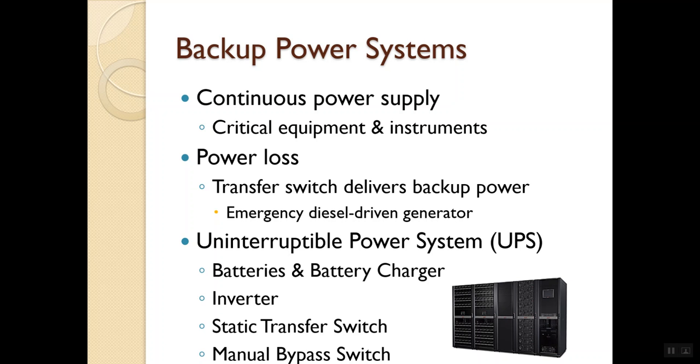And so what we do in industry is all the operator stations, all the control stations, run on a battery all the time. That battery is constantly being charged, so we are constantly being fed through a battery. Then if we do lose power, the computers don't see anything different. They're still running off the battery. The only thing different is that the battery's not being charged right now.